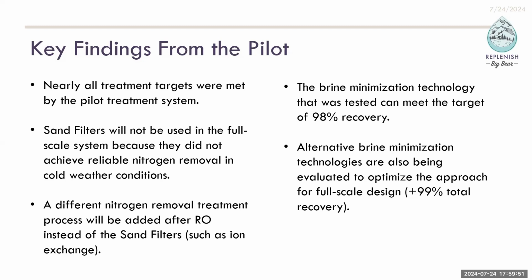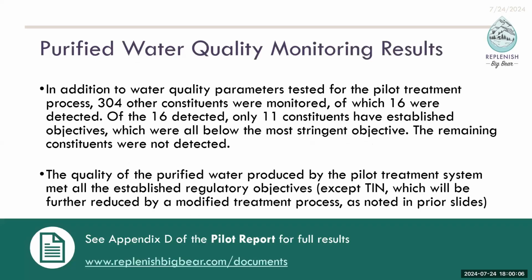The softening one we did do bench scale tests on, I mentioned earlier, and the preliminary results showed 99, I think 0.2%. So 0.5% higher than what we achieved with the pilot. Yeah, total recovery, thank you. The two RO systems did meet their 90% objective. One of them only for a short time, had to go back to 86%. But yeah, that total system recovery wasn't that.